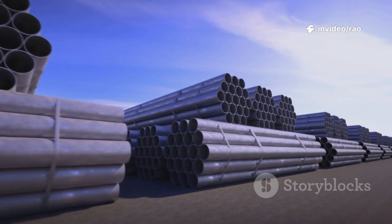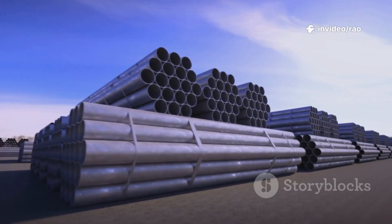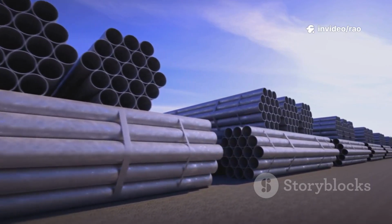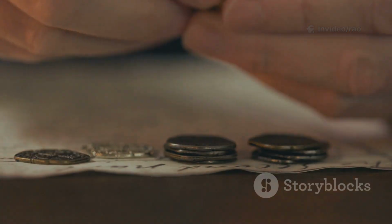You cannot place a fraction of a bar on site. Therefore, we must round up to the next whole number to ensure coverage and spacing of 150 mm. So we will use 28 distribution bars.